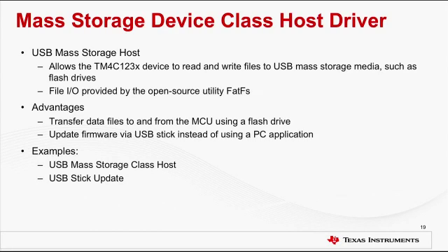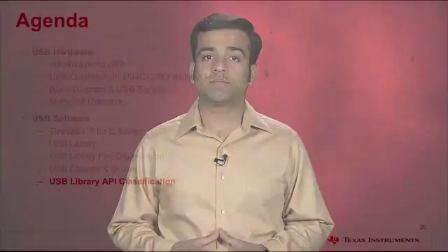The APIs in mass storage class allow the USB mass storage class to call an external set of functions that actually perform the operations on the physical storage media. The USB library's mass storage class also provides an interface to inform the USB library when the media status has changed in the case physical media can be ejected. This is important for devices like SD cards that can be removed before the device is connected or even when the device is running.